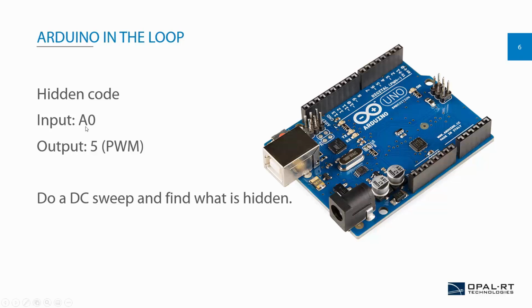In this case, the DC sweep would be to sweep from 0 volts, wait, measure the output, 0.5 volts, wait, measure the outputs, 1 volt, wait, and measure the outputs. This kind of process would be very time consuming to do manually. Therefore, we use TestView for this example.